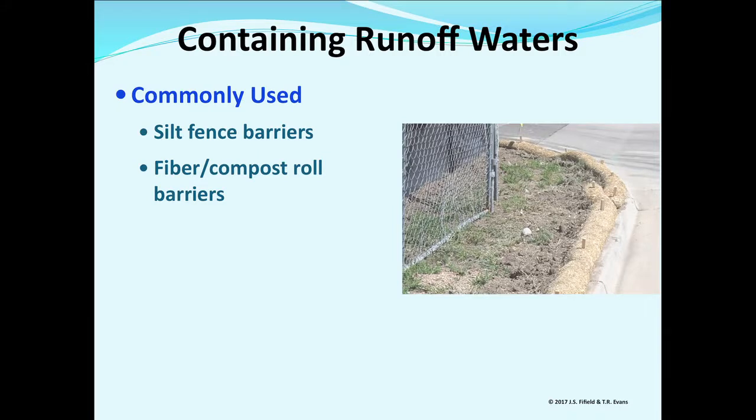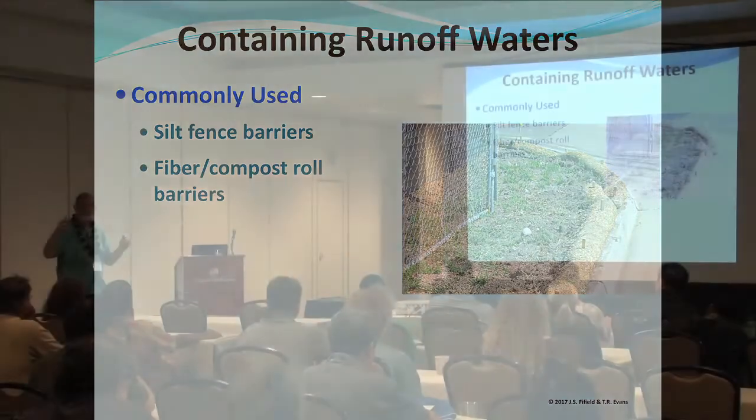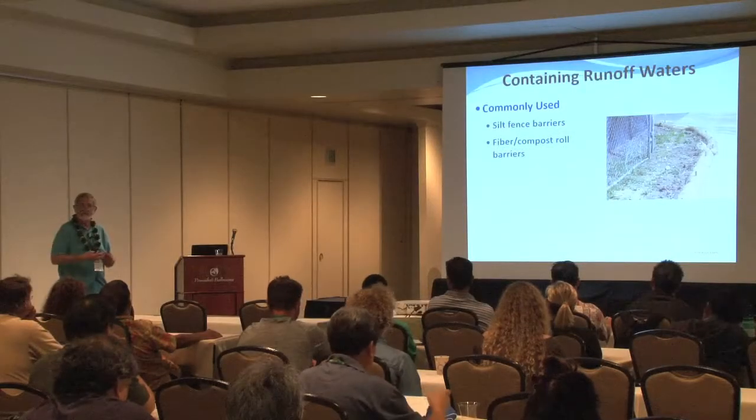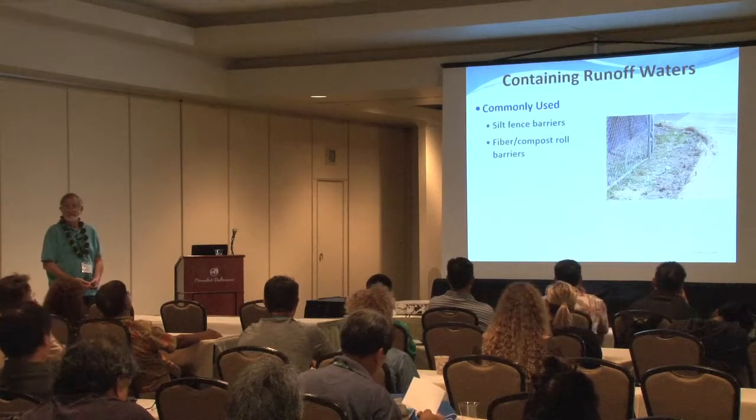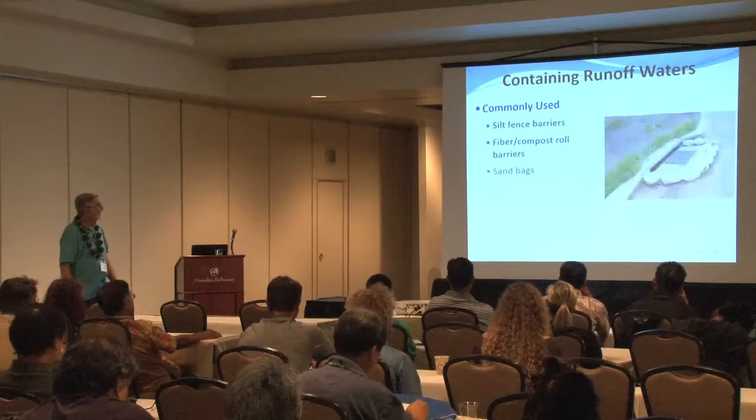Fiber rolls. You use a lot of fiber rolls around here. And I said last time I was in, I think it was in this room, I've been running from room to room. If you can lift that fiber roll up, it's not going to be effective with one hand, that is. You're going to have to either weight it down or soak it or something so that the internal stuff can become very saturated so it hugs the ground. So keep all these things in mind as we go through.